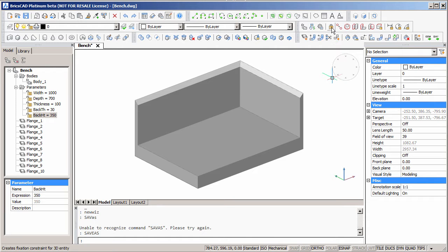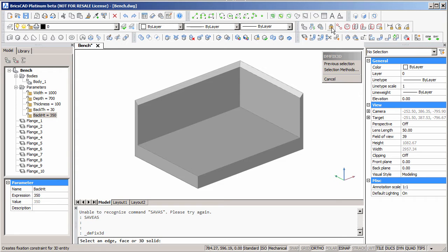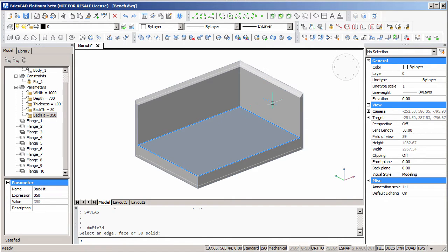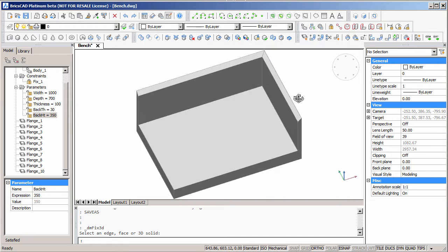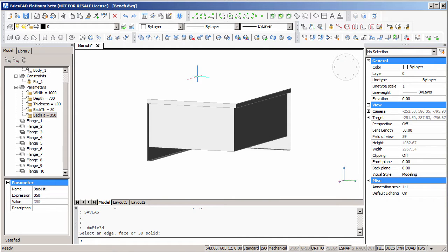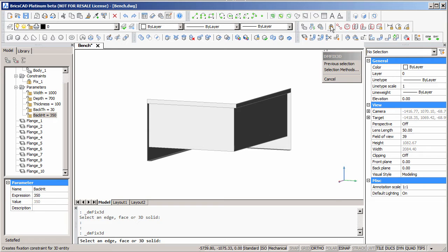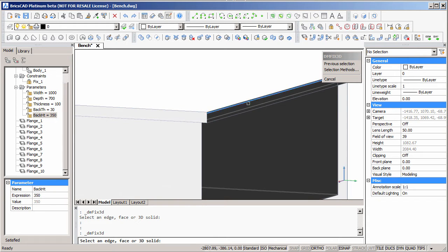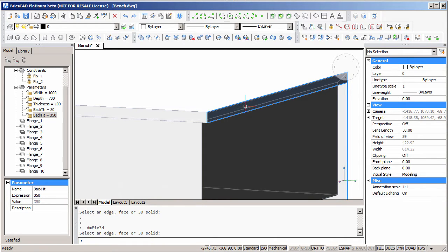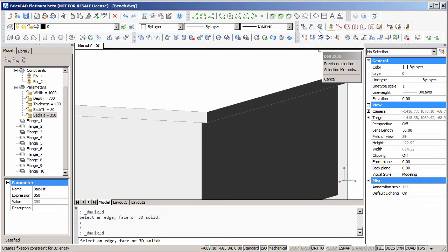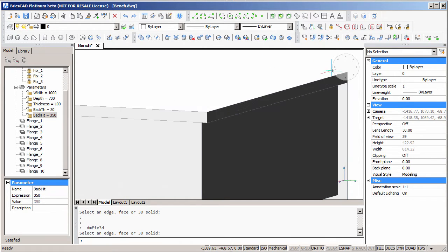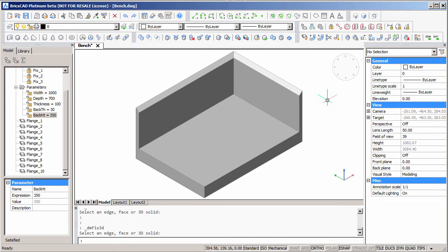First of all, I want to fix the origin of the model. So we designed this so that the workbench is sitting at the origin, the top surface of the workbench, and the two surfaces at the back of the splashback, which are going to be fitting into the corner of the room. So those three surfaces will never move. Those planes will be maintained.